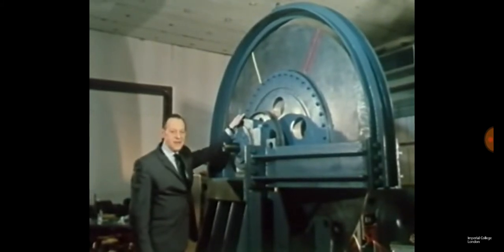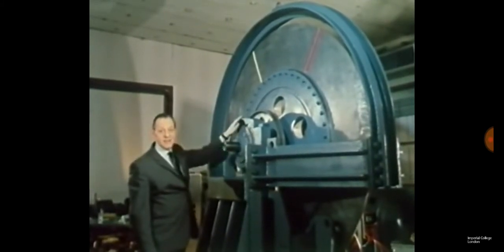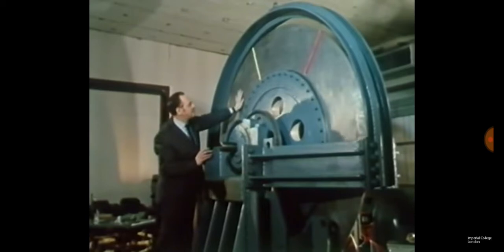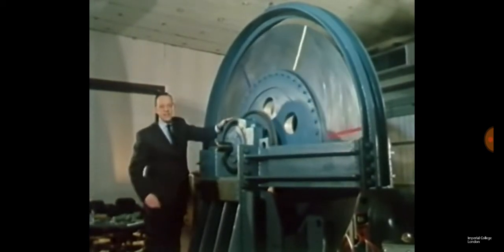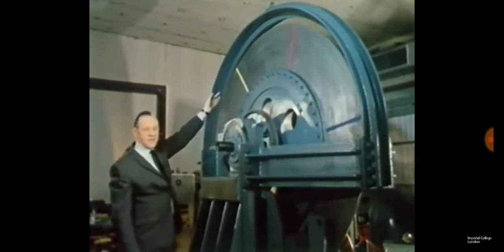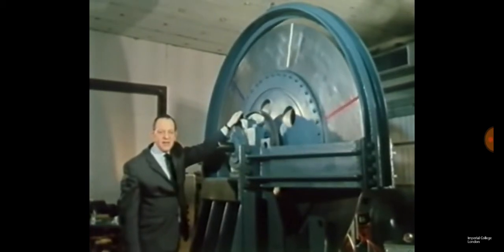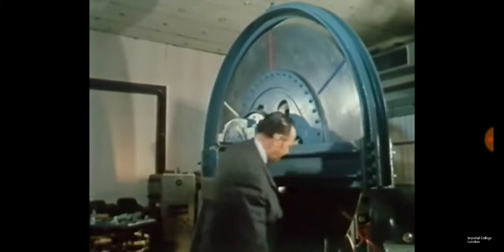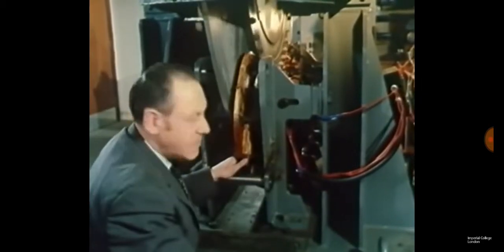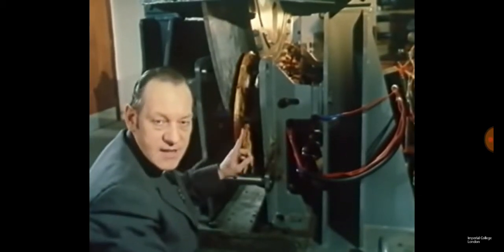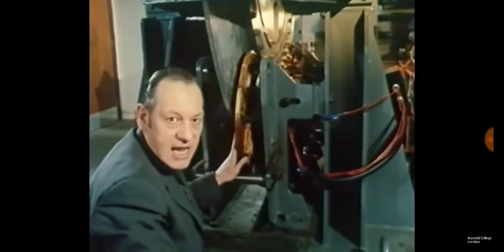Now, I don't have to tell you that this is a big motor. In fact, in terms of diameter, it's one of the biggest made. Its rotor is this aluminium disc. So it's an induction motor, and therefore an electromagnetic machine. And in spite of the fact that the moving part is rotary, it is a test rig for linear machines. Let's have a look at the driving unit. This row of coils is a linear motor which has been bent slightly to fit the shape of the disc. The speed of the field on this motor is nearly 300 miles an hour.